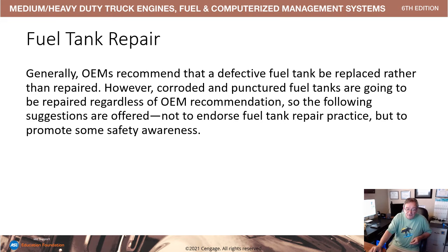OEMs recommend a defective fuel tank be replaced rather than repaired. There are some recommendations for welding, but it's not really common in the average shop. Usually specialty welding shops would perform that.